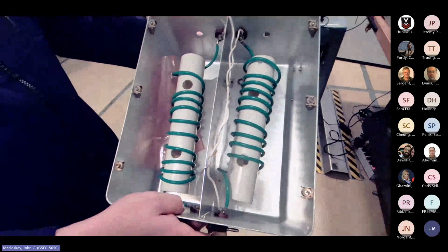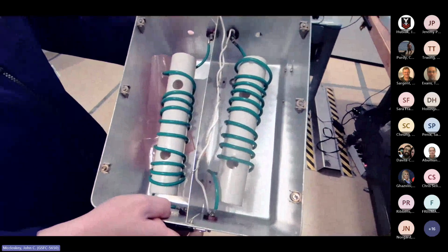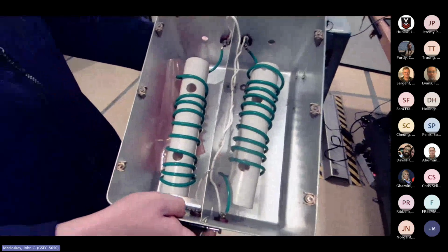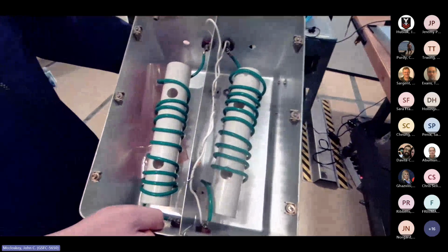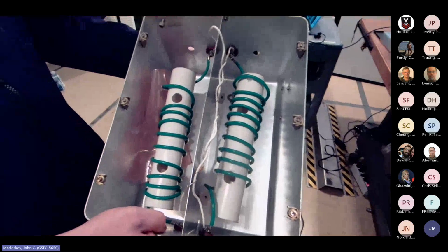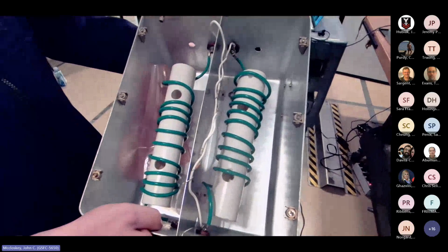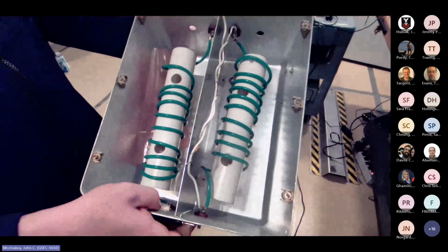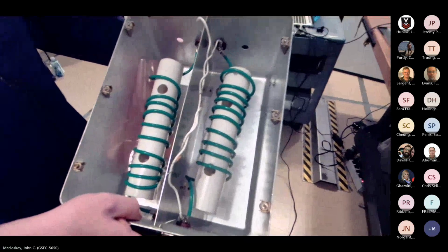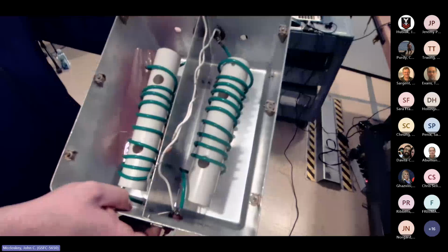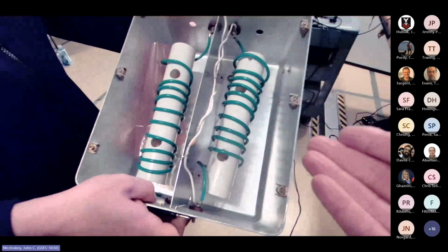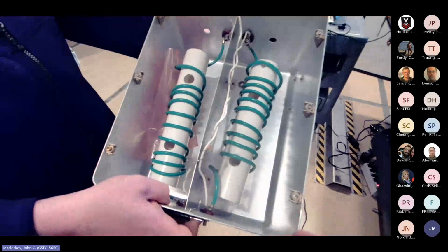I did procure one for JWST. I specified it, and the program specified it, but I fed the impedance specs to the vendor, and they built us a nice LISN that worked for our system level testing. But it was probably about $10,000. But there was somebody who actually knew what they were doing and could devote the time to doing all the tweaking and the different iterations of this to get it right.